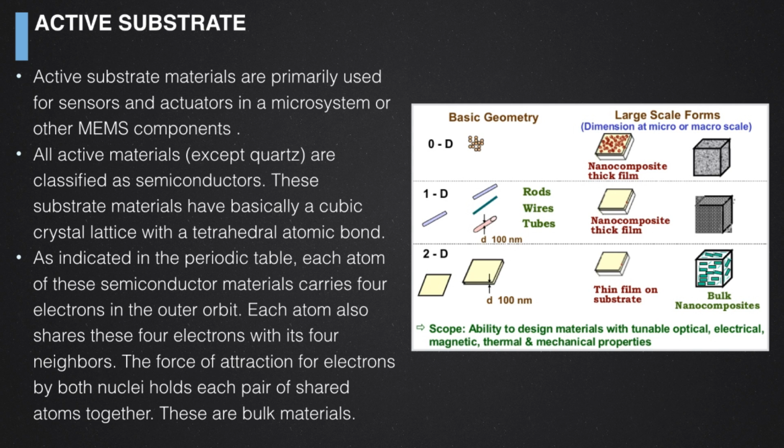We may also think of having a 3-3 coordinated composite material, where we have interpenetrated and fully connected bulk components realized by 2 non-miscible materials. An example of this is the bulk heterojunction solar cell, where you have a polymeric material that has a behavior like a n-doped semiconductor, and another one that has the p-doped behavior.